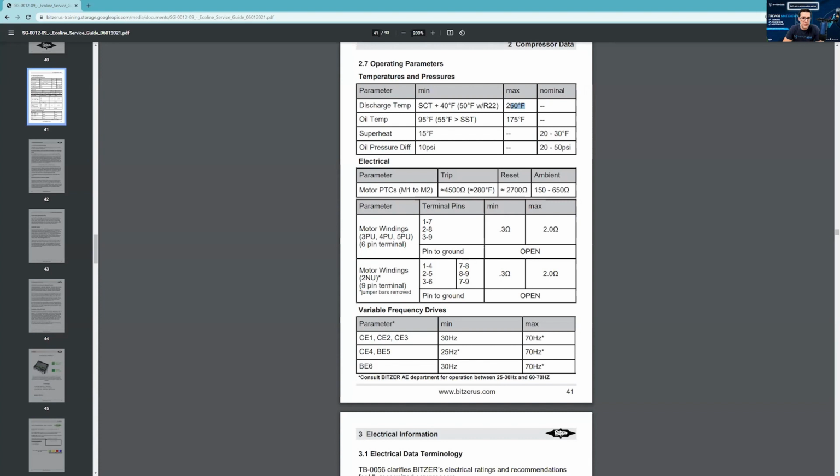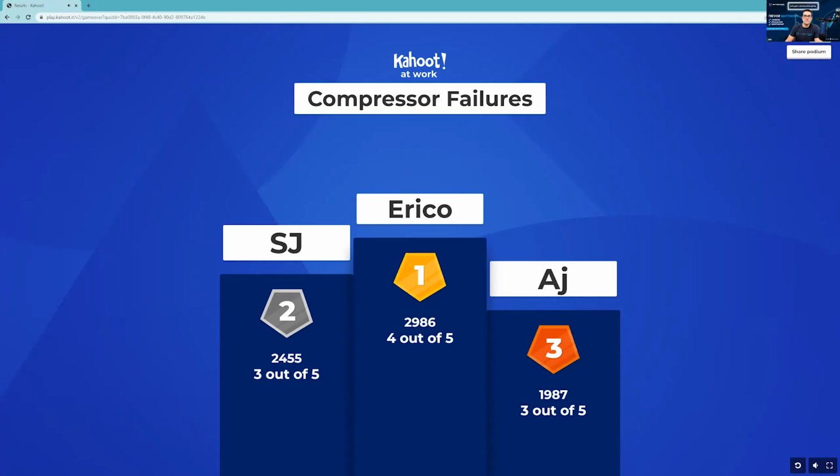You can go into the application engineering bulletin for the 4 and 6D compressors and find the right one. It'll tell you the different thicknesses for the compressor. I think there are 4 different thicknesses on that 6D, depending on the temperature application or something like that. If I remember, that's going way back. But yeah, there was a choice. You've got to make sure you get the right one. That's a great question. Awesome.